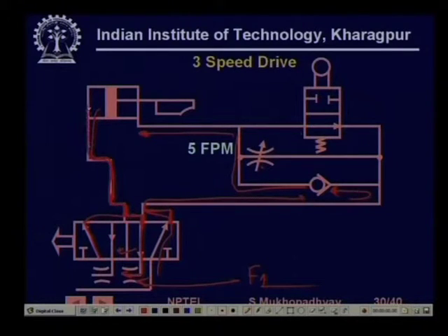So, it will flow through this into the cylinder freely, and then while coming out, initially, see, this is a cam operated, this is a cam, actually this cam and these are mechanical linkage. So, initially this cam is not operated. So, therefore, this is the position. So, it flows through the valve and returns and flows out through this path. So, the flow rate is F2.